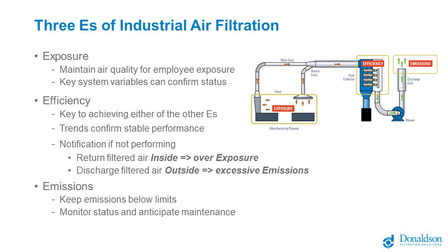Also, you want to make sure you recognise the impact of design changes to a system that's already in place. For example, it might be a good idea to add a secondary or a HEPA filter to minimise the risk of excessive emission. However, adding this level of additional restriction will impact the overall volume in the system and could reduce the capture velocity and thereby increase the exposure levels of the employee. Performing ongoing monitoring of your system, such as maintaining the design flow, tracking the filter life and the filter loading, and detecting the early onset of filter leaks, will help monitor the overall system and its status, and thereby reduce the risk of unplanned operational downtime.